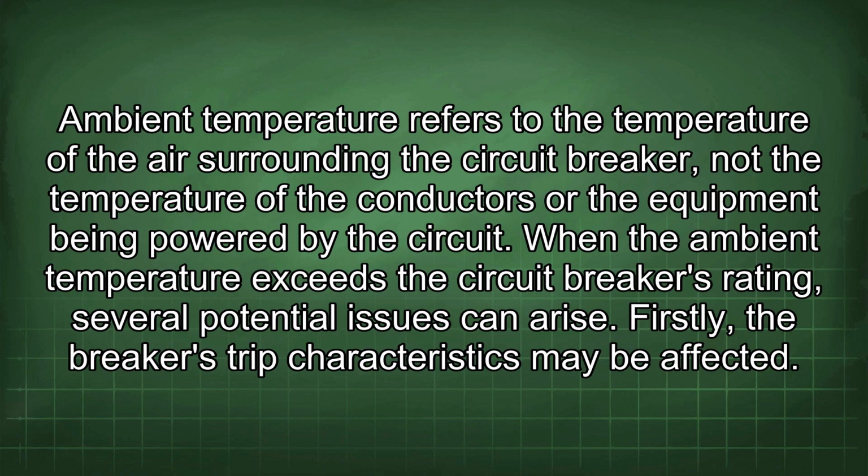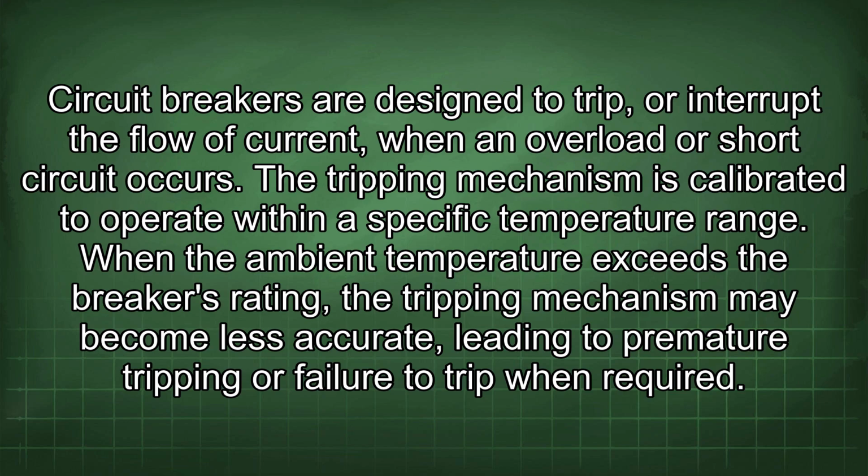When the ambient temperature exceeds the circuit breaker's rating, several potential issues can arise. Firstly, the breaker's trip characteristics may be affected. Circuit breakers are designed to trip or interrupt the flow of current when an overload or short circuit occurs. The tripping mechanism is calibrated to operate within a specific temperature range. When the ambient temperature exceeds the breaker's rating, the tripping mechanism may become less accurate, leading to premature tripping or failure to trip when required.